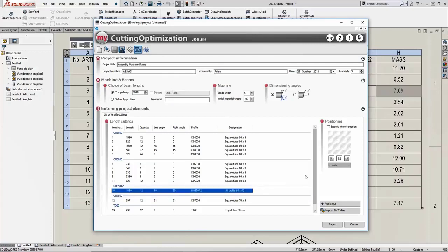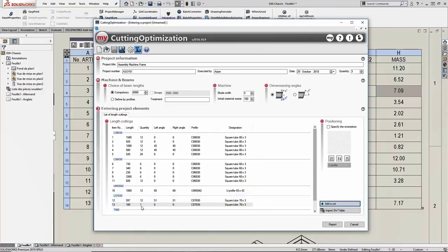We can also go ahead and change the profile orientation if a profile needs to be a certain way round for manufacture, for example. We can go ahead and choose the profile type and then rotate it to get it to the right angle. If we require additional lengths inside of our cut list that aren't actually in our project, we can go ahead and select those.